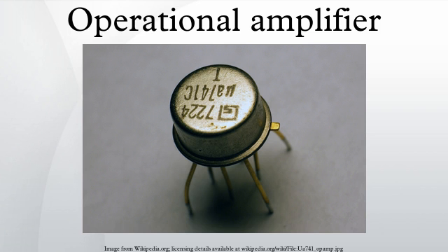A zero voltage level detector can convert, for example, the output of a sine wave from a function generator into a variable frequency square wave. If VIN is a sine wave, triangular wave, or wave of any other shape that is symmetrical around zero, the zero-crossing detector's output will be square. Zero-crossing detection may also be useful in triggering TRIACs at the best time to reduce mains interference and current spikes.